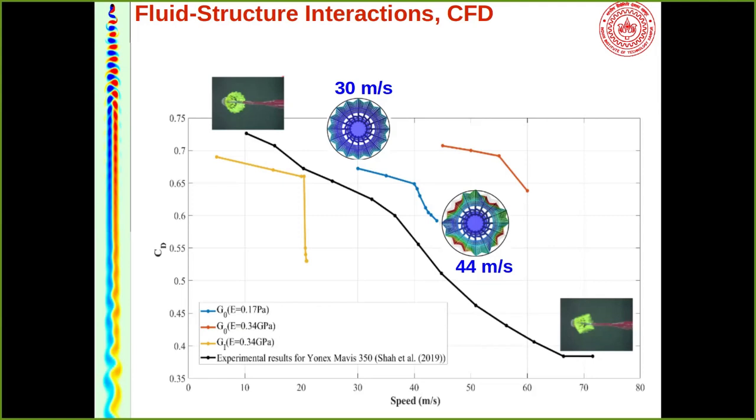There is first some kind of axisymmetric deformation, then actually it buckles. And we see this feature in the wind tunnel experiments also, which we missed earlier. After the numerics, we saw that yes, there's a change of slope. So this is an instability, buckling. And then, of course, we are not able to do calculations beyond this because the mesh becomes incomplete.